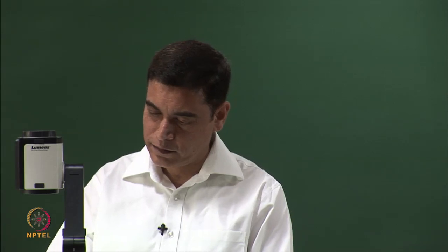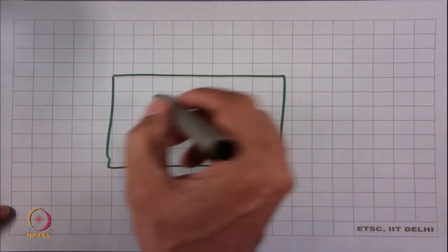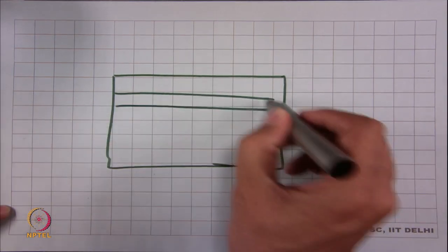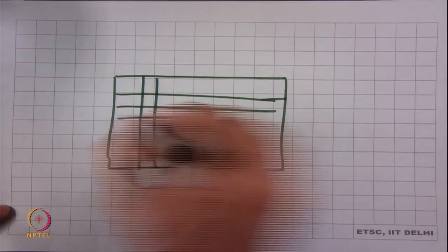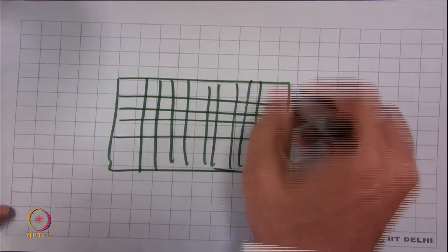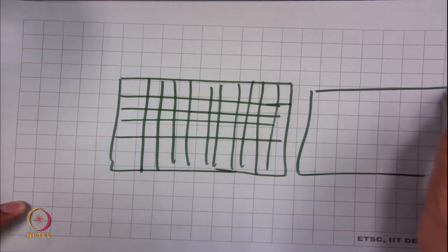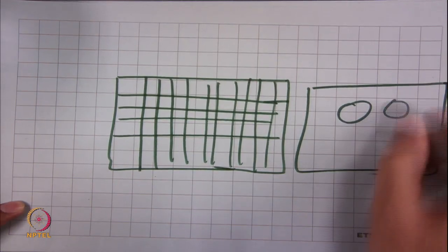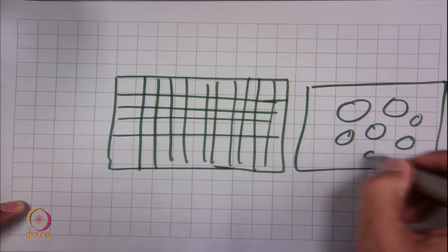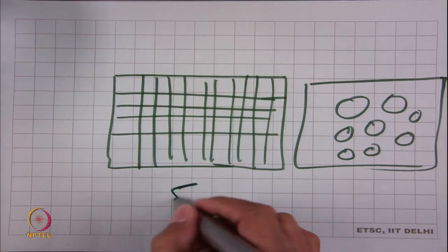So if you have, let us say, these are the tubes and these are the different fins. What we find a very simple way to do is take a piece of cardboard and just make holes consistent with 50% blockage. This is put over this, and the unit is tested at 50 degrees centigrade.